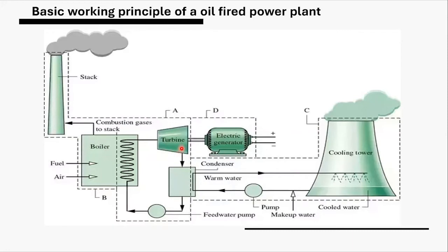Also, an extra information, the condenser needs constant cool liquid. Cool liquid is supplied at the condenser with the help of a cooling tower. The heated up water from the condenser outlet is sprayed in the cooling tower, which induces a natural air drift and the sprayed water loses heat. This is how a colder liquid is always provided at the condenser inlet.